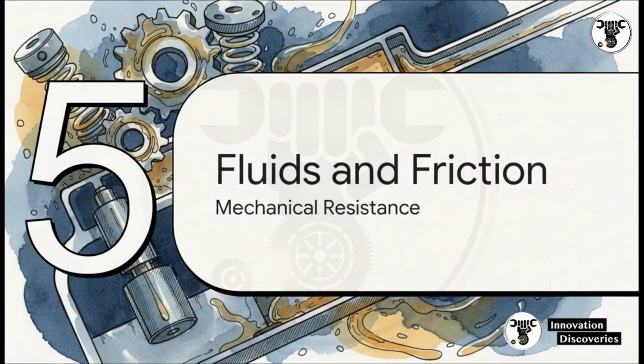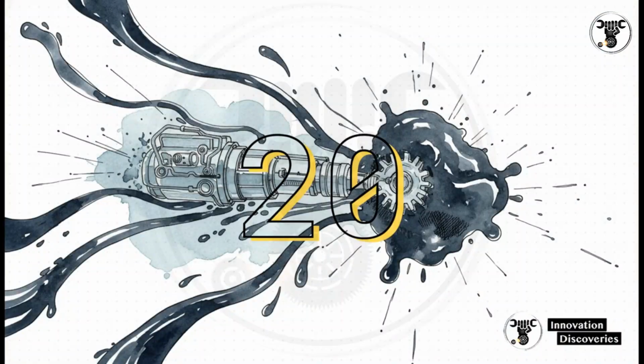Section 5. Fluids, friction, and failures. I want to let this number just sink in for a second. 20. At negative 20 degrees Celsius, automatic transmission fluid can be up to 20 times thicker than it is at normal operating temperature. That creates massive hydraulic back pressure. Your transmission solenoid has to fight through a fluid that has essentially turned into syrup, which directly adds a massive amount to the actuation delay.